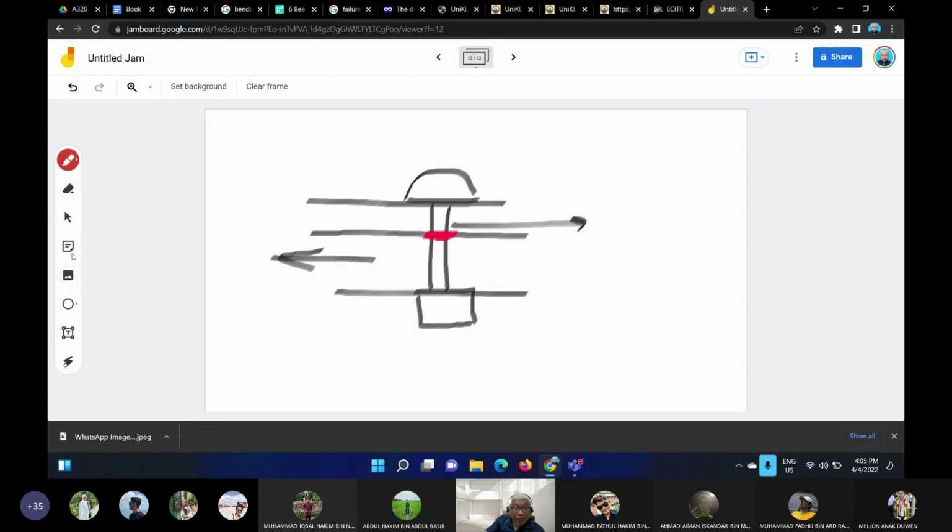So again, it's just like any other. The shear load on the fastener will be the ultimate shear stress times the shear area. Then you get the fastener load. That's how they calculate the fastener strength, by multiplying the area and the ultimate shear strength.